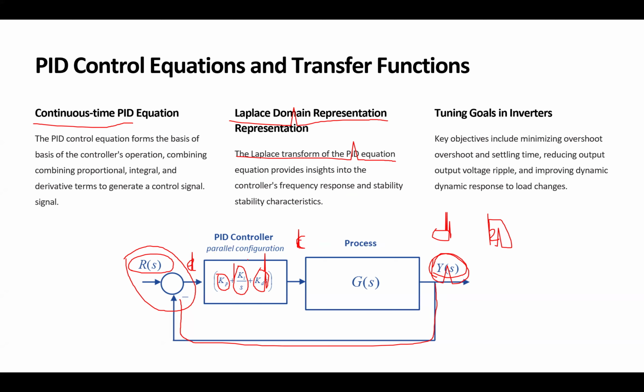Based on the parameters Kp, Ki, and Kd, which are our levers to control the correction signal, we can tune them to minimize the variance, overshoot, and settling time, and get to the targeted point as fast as we can. Is that clear?